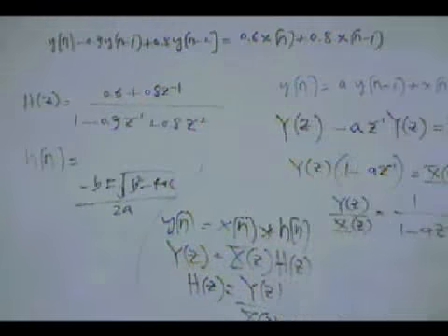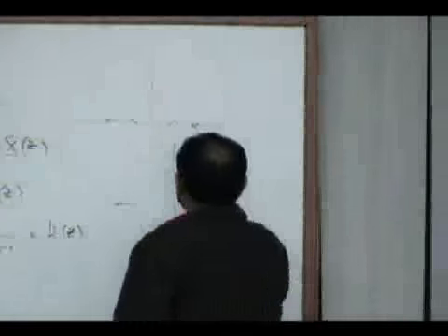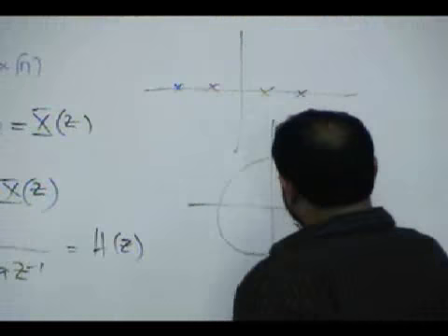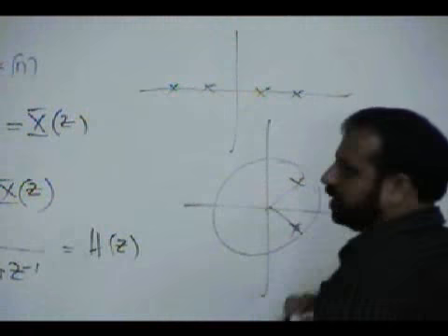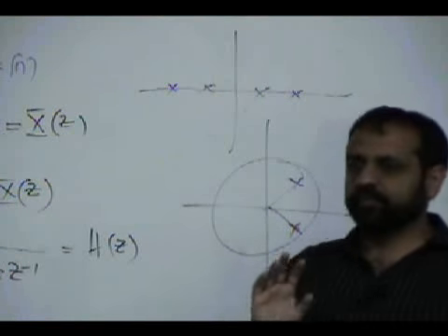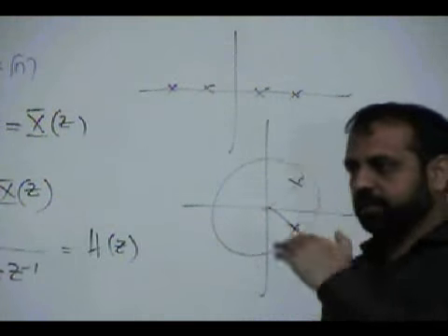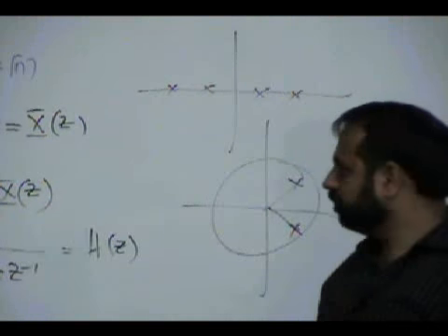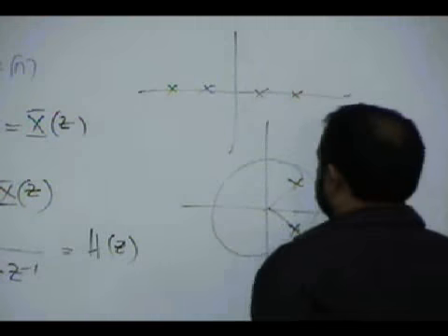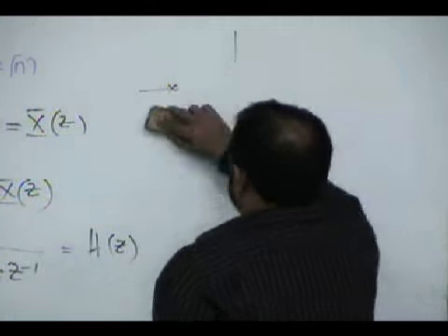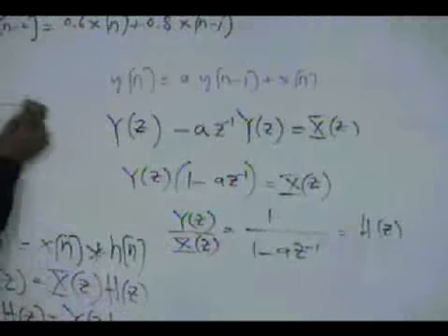Okay, the poles will be real, or if they are not real, they may appear here, but if a pole appears here, a pole will also appear here. Guaranteed. For a real coefficient difference equation, poles will appear as conjugates of each other. We'll spend a lot of time learning about all these poles and zeros.